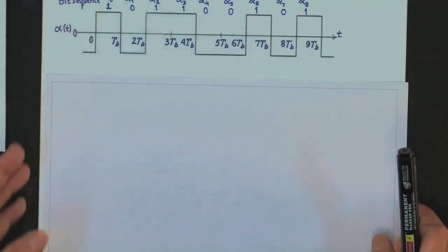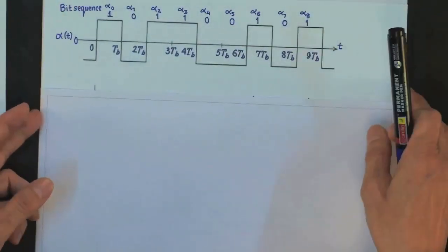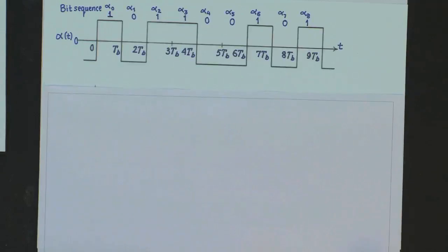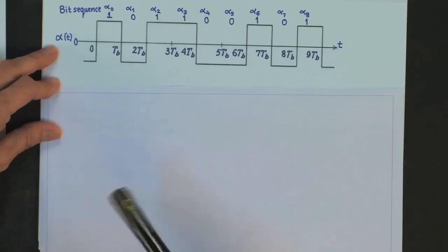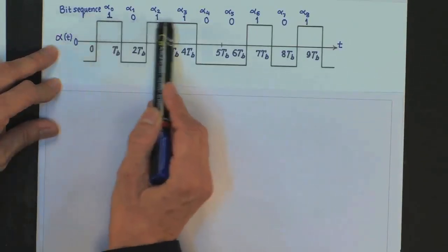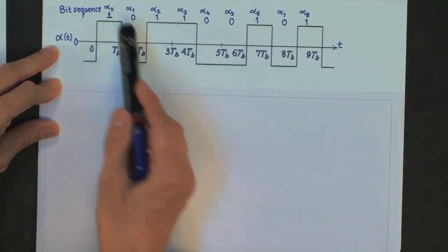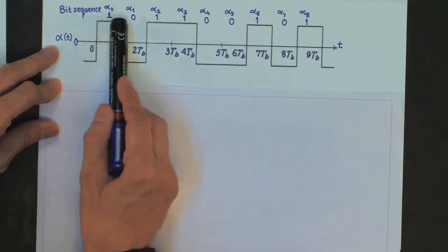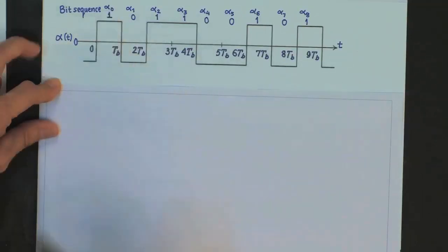This alternate representation of QPSK helps us to implement QPSK easily in practical applications, and the principal operation is as follows. Given a bit sequence 10 11 00 101, the information bit stream is first converted to a non-return to zero waveform with plus minus 1 levels.